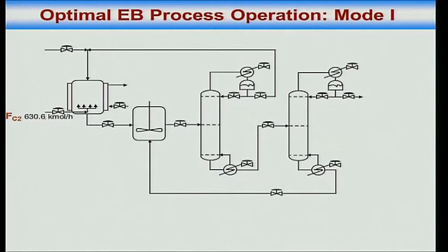If I look at the active constraints, reactor 1 should be operated at maximum level and at maximum temperature. Reactor 2 should be operated at maximum level. Also, the impurity in the product should be at its maximum allowable limit. What is the impurity in the product? Any C6, any benzene that leaks down here will be guaranteed to end up here, plus whatever is the split done by the second column.